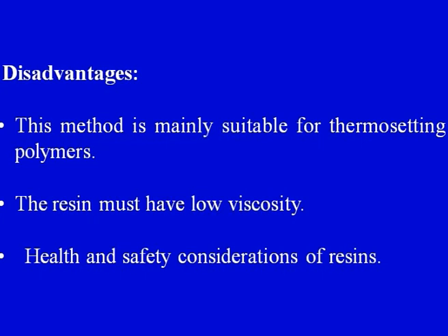The resin must have low viscosity, and then there are health and safety considerations also involved, because we are doing the things manually, we are touching the fiber with our own hands. Suppose we are using glass fiber, it is abrasive in nature, and it may have some health hazards. Glass fiber is also sometimes carcinogenic in nature, so again there are few issues involved there. The resin and the catalyst, when they are reacting, there may be few fumes, or there may be some gases generated, which may not be too good for our health. So there are some health and safety considerations.